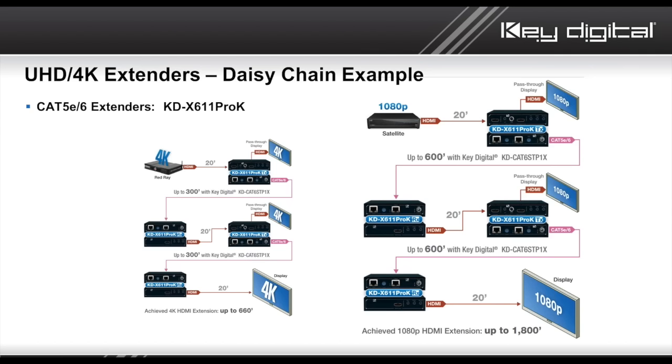We could use an HDMI cable up to 20 feet long coming in. And the pass-through feeds a local monitor where your Cat5 then feeds the next unit as we follow down. That RX HDMI doesn't feed the monitor there. No, it feeds the next transmit with a cable up to 20 feet away if needed. And that pass-through feeds that monitor.